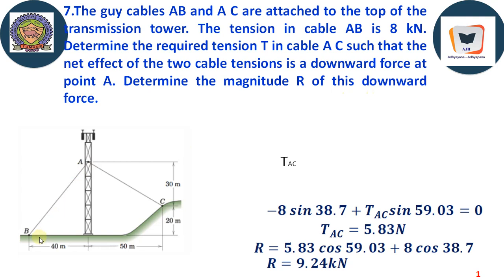There is a given tension value, and we are asked to find out the tension in AC, given that the resultant will be acting vertically downwards at A. Therefore, the direction of the resultant is given. It is a lone vertical force with the horizontal component missing. Therefore, we can make use of the principle that we laid out in our tutorial number 2.